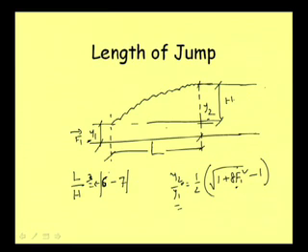For most of the portion it will be from 6 to 7, not 5 to 7. Some books, in some experimentation, found 5 to 7, so the average value is considered as 6. We also conducted one experiment, and there we could see that this length height ratio also depends on the slope of the bed. Other investigators also conducted that sort of experiment and observed that.